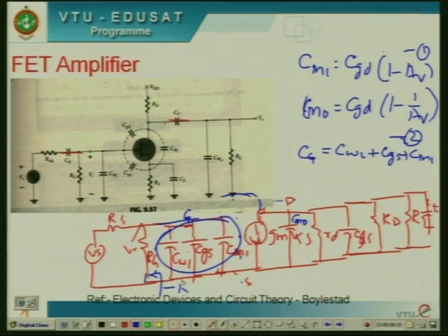For the Thevenin's equivalent network of a transistor amplifier network, you have to set Vs equal to 0. When Vs is equal to 0, this is acting as a short circuit. Then if you observe this, when looking at that, only one resistance is connected, the other is an open circuit, then these two are in series. Therefore, the resistance looks like R signal plus RG, or RTHI.